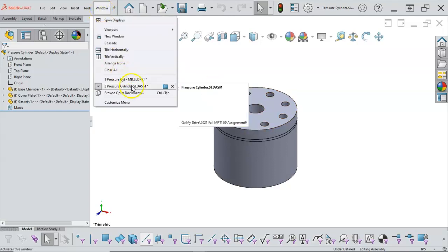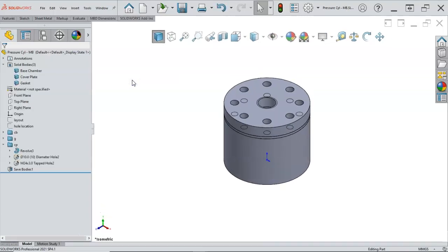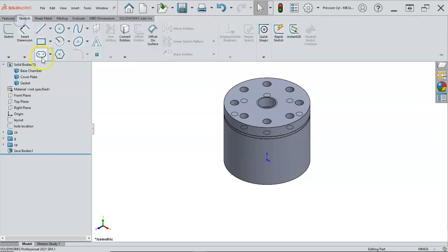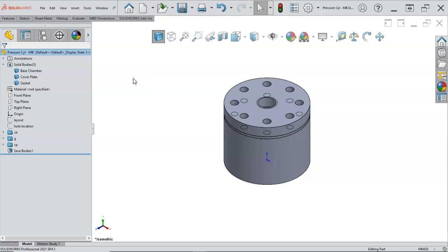The other thing is, if I didn't need the assembly, I didn't need all of the individual parts for whatever reason, but I did want to show this with the Hex Set, I would probably just draw a 13mm hex polygon on the top, extrude it out 6-8 millimeters, I have to look at the ratio there, and then pattern it around.